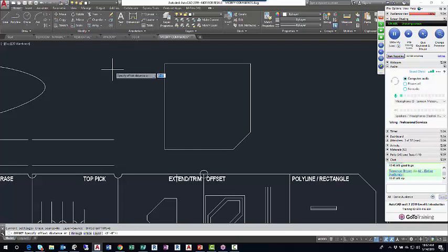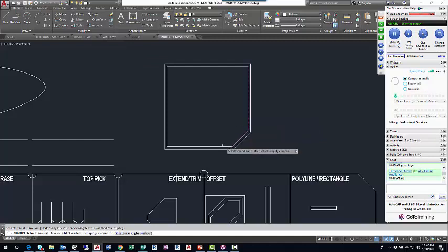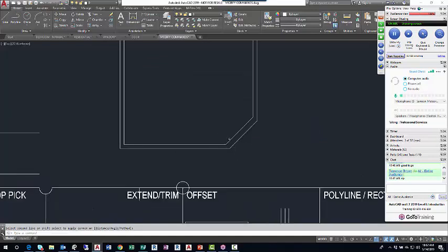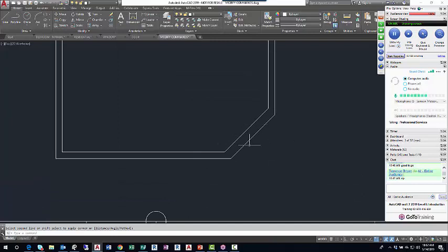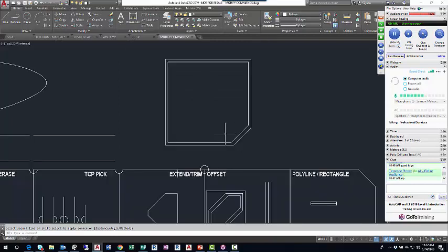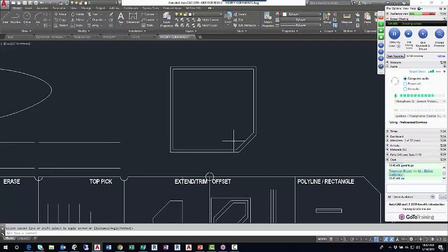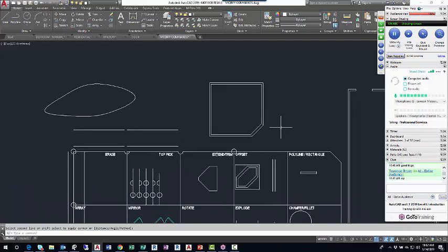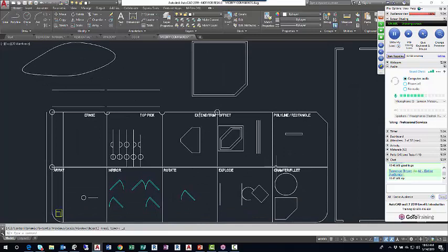When we go to create the chamfer for the inside of the closet, it's going to be most effective to just offset. Use the offset command like so, and that'll create the illusion of a wall thickness in that chamfered wall. If we were to try to chamfer the interior wall with the same chamfer distance, there we go, it creates a little bit of an overly thick wall, thicker than 3.5 inches. So offset is probably the easiest way to maintain that 3.5-inch thick wall.